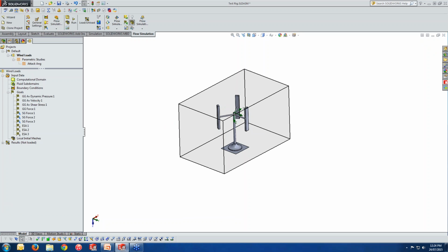This case is simply considered a wind tunnel as we set up, with 12 meters per second in the X plus direction here. What is very important is that we are always trying to achieve an optimized simulation. In this regard, we have to make the software trace some parameters which are very important, to calculate precisely, and also to make the mesh resolution suitable.